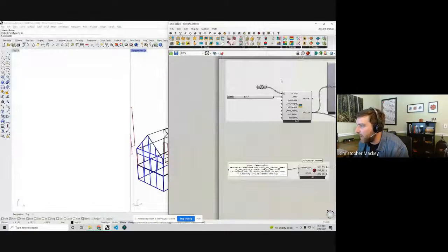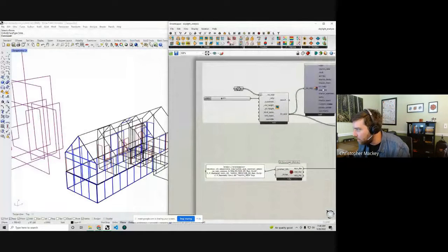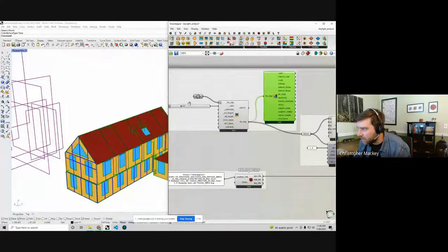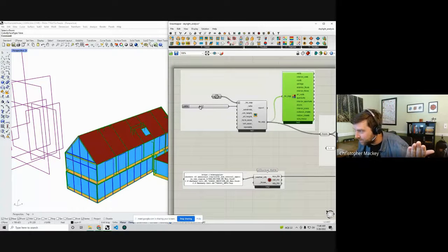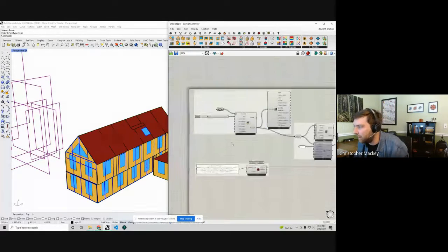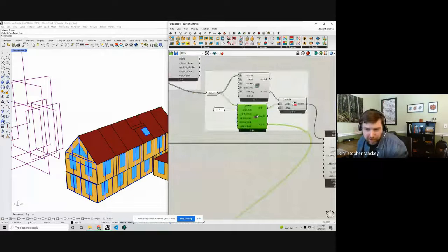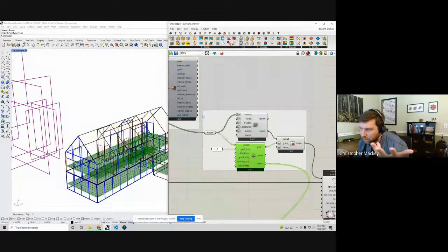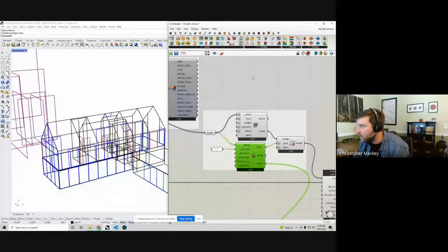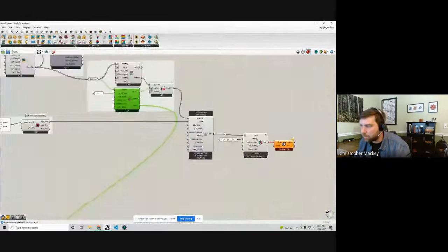In this case, I've actually selected all of the rooms in the model here. And you can see I can adjust the glazing ratio of everything all together. So I can do a 90%, oh my gosh, glass box, or I can go down to 30% like that. I'm assigning some sensor grids so we can actually look at the daylight in the space. If you wanted to take a look at those, you can see what they're like in Grasshopper, and make sure the grid size is good. But let me just push this to Pollination right now.